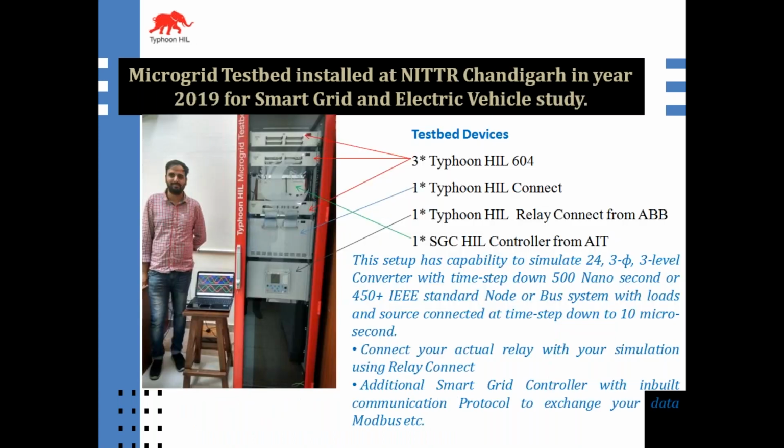The second microgrid testbed is installed at NITTR Chandigarh in the year 2019 for smart grid and electric vehicle study. Here we can see that we have also used three Typhoon HIL 604 boxes and one Typhoon HIL HIL Connect. The only difference between the microgrid testbeds installed at Kanpur and Chandigarh is that here we have used the smart grid controller's inbuilt communication protocol, Modbus, to exchange data.